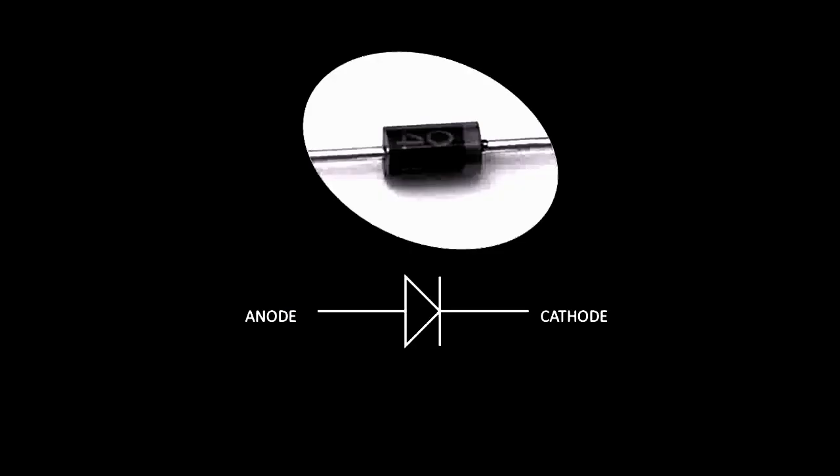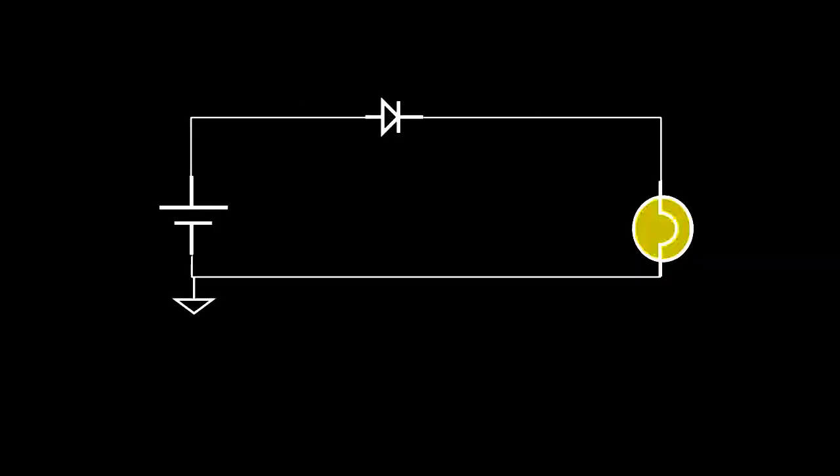And that's it. Now the second component I'll be using in my computer is a diode, and this is what it looks like. I'll be using 1N4007 rectifier diodes. While the physics of this device is quite complex, and there's a lot of maths you can go through, for the scope of my project, all you need to know is it's got 2 terminals. If the voltage at the anode is higher than the voltage at the cathode, then we say it's forward biased.